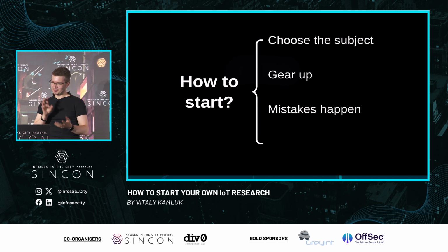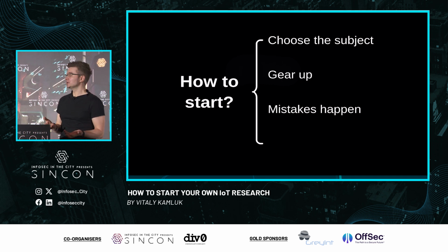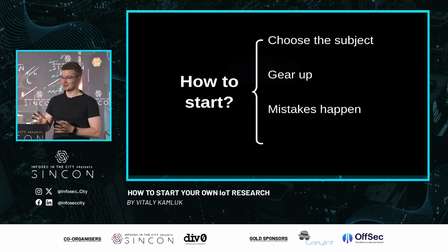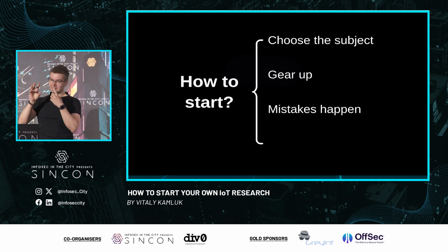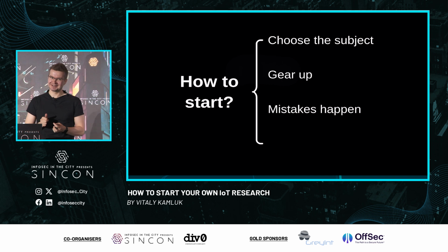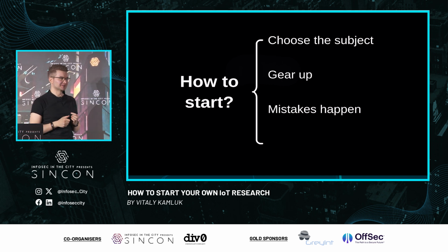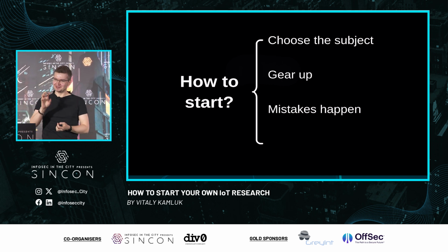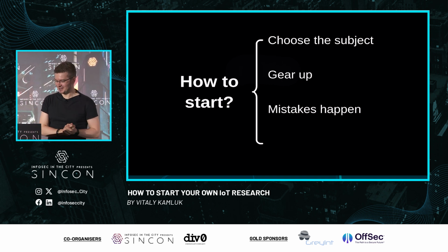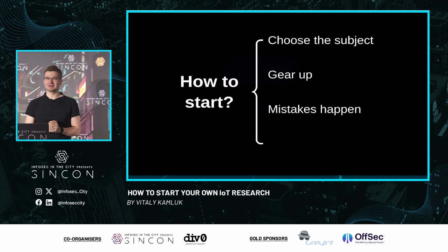So I put it back, and then I started the device. It didn't work. It just made some buzzing sounds, like to the speaker, like bzzz. And I thought, well, that sounds bad. Probably I'm bad at soldering. And eventually I figured out that, according to my notes, I confused the up and down of the chip. So it was actually soldered upside down. Luckily, it didn't burn the chip or the system. So I unsoldered it and soldered it back properly. And it kept working. Fortunately, I can't show you today, but it did work without any issues.